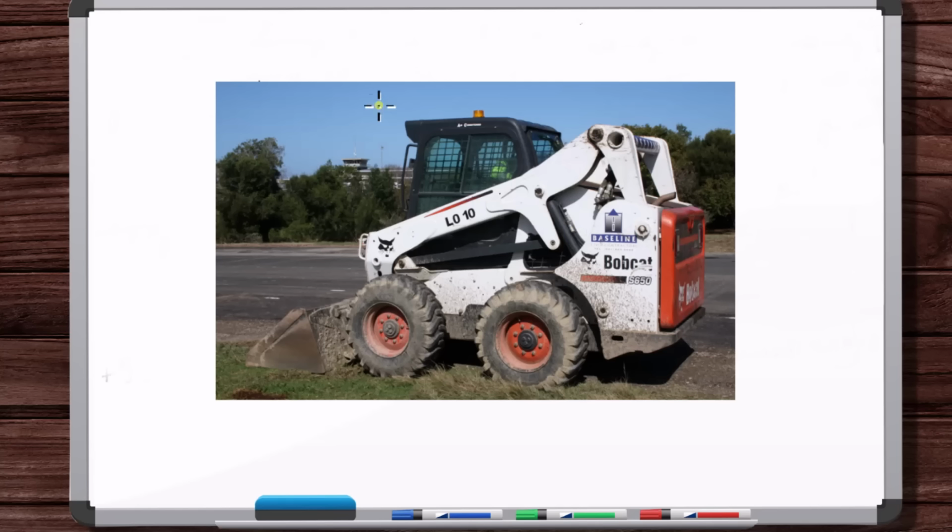Or the designers might say another potential worst-case scenario is the bucket is overfilled, it's raised up high, and then it's accidentally dropped full speed. Midway down, it's the largest acceleration, so you'll analyze this from a dynamic standpoint. When it's on its way down, it's accelerating, you take a snapshot and you bring this component into empty space.